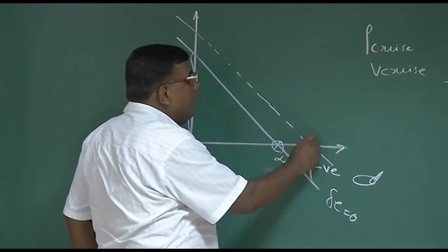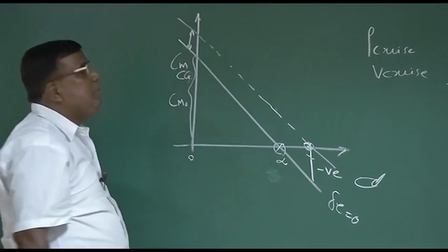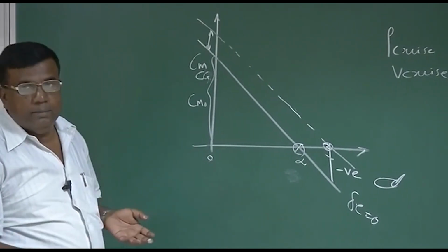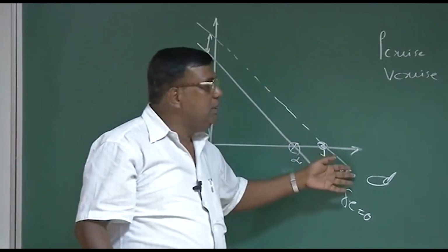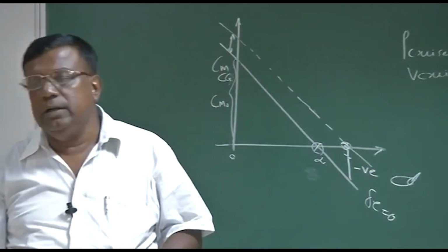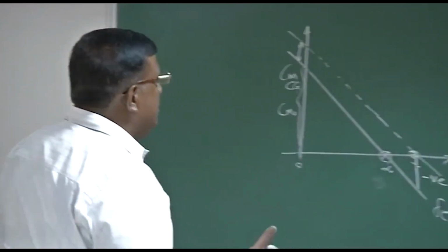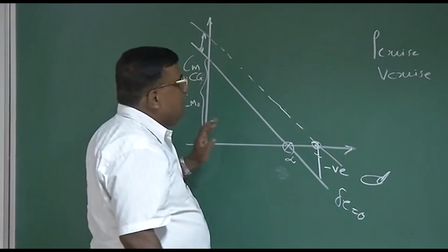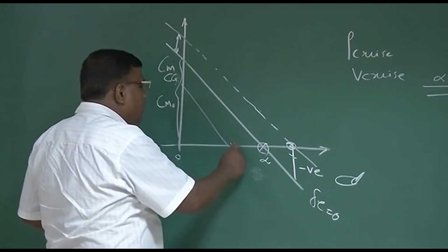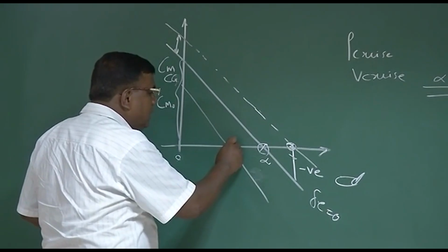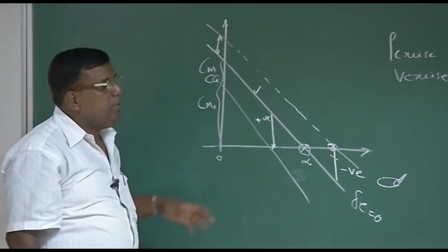So now again it is a trim point, and effectively you could see that by deflecting the elevator I have increased the Cm naught value. So this is a control problem. Okay? So this is called the control aspect of the airplane, and there is a limit to which you can deflect the elevator, typically for a normal configuration plus minus 25 degrees. There are mechanisms to increase that also. But the physics should be clear, the mechanics should be clear. If I want to fly here, as far as the basic graph is concerned, this will generate a positive moment. So I have to counter it.